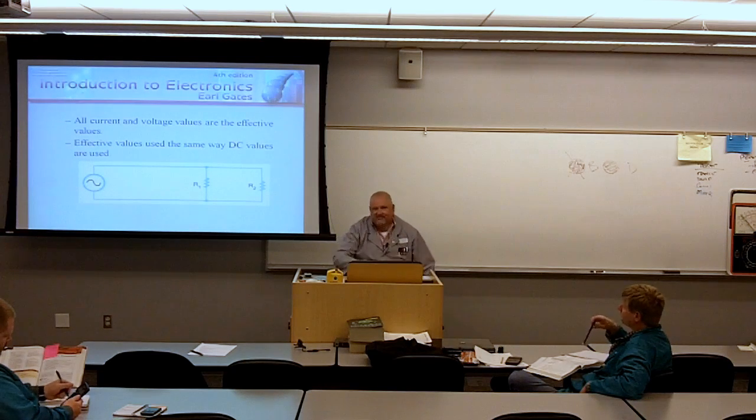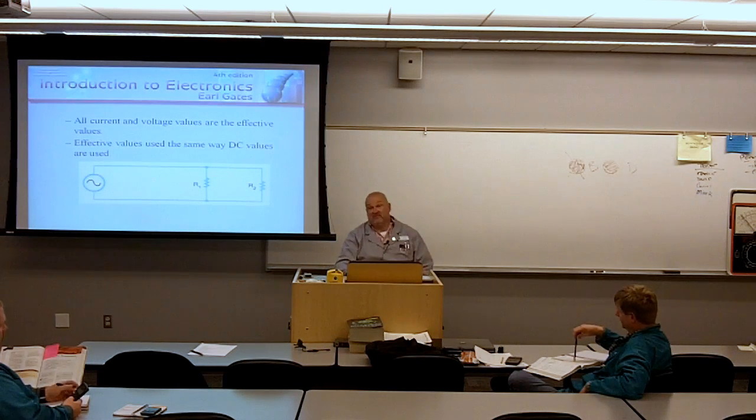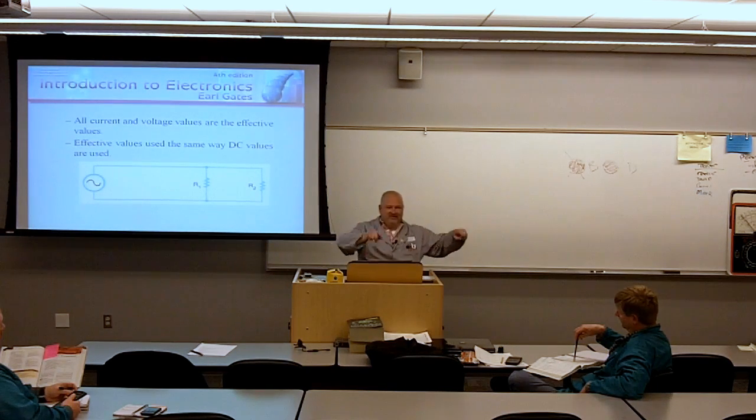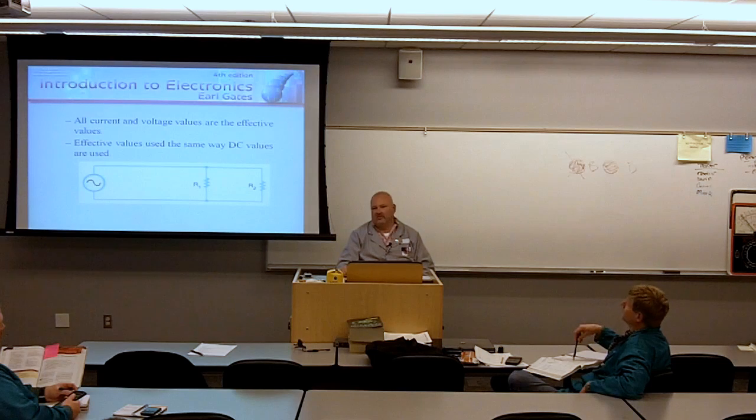But for a ship like that, it's got a big generator. You want to make sure that you synchronize everything, and they actually have small meters that allow them to synchronize the phases, so that when you switch over, everything's still in phase. Because you could destroy motors and stuff by giving them a goofy phase relationship. So that's why you do that.